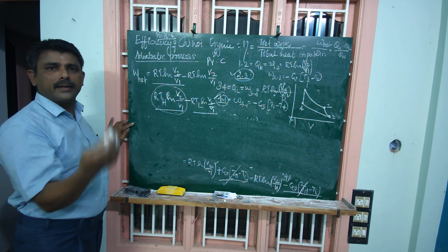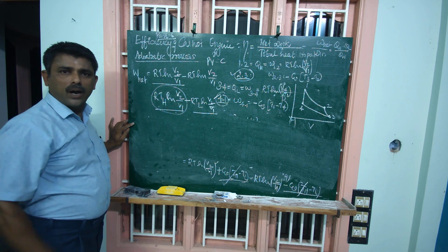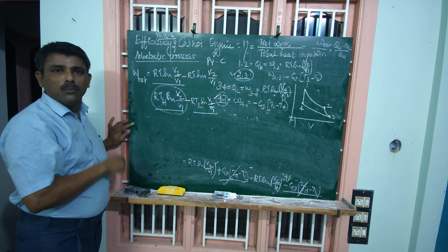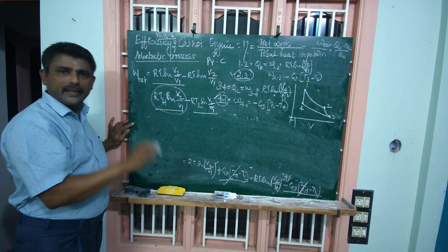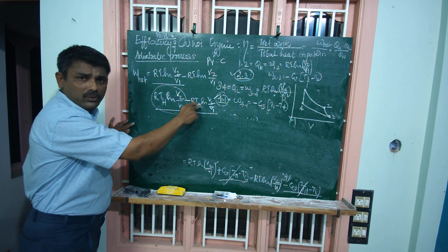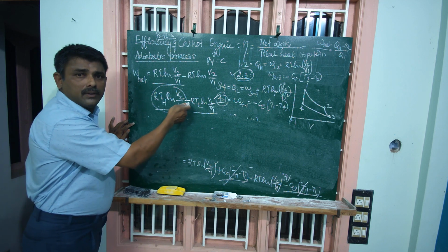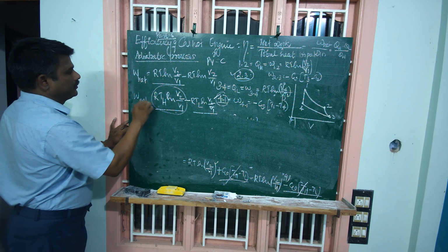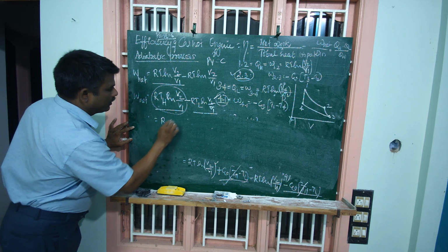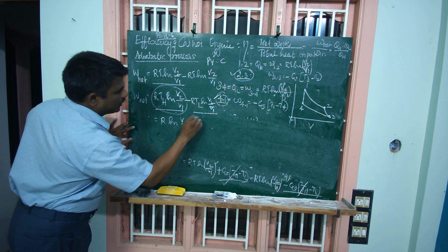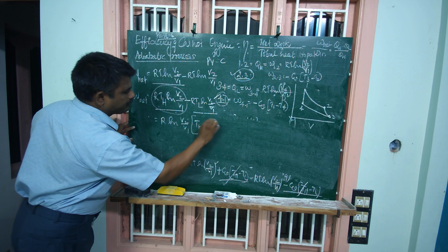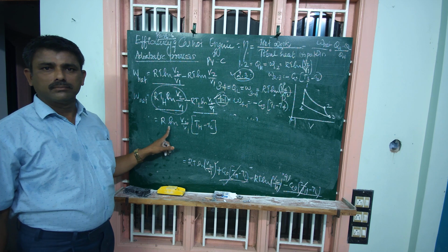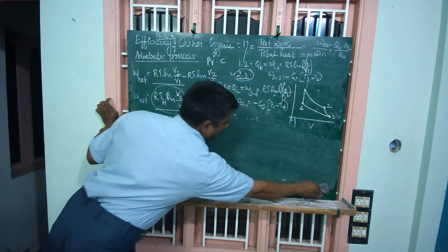Work done by the system, heat transferred to the system. Listen, this is minus. Automatically it will be clear. This is the amount of work done on the system, minus sign. Moreover, the work produced, the amount of heat, exactly gets transferred from engine to sink. Hence, minus sign. Clear? Work, heat, heat, work net. This is R ln V2 by V1 into (TH minus TL). Net work done. Clear? Next, total heat input for efficiency calculation.